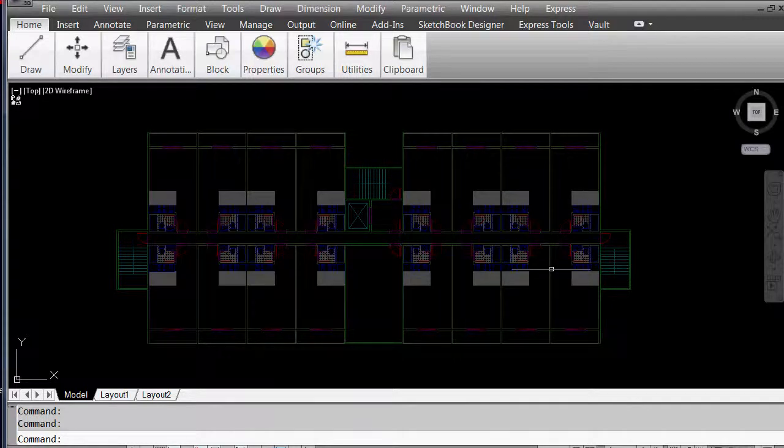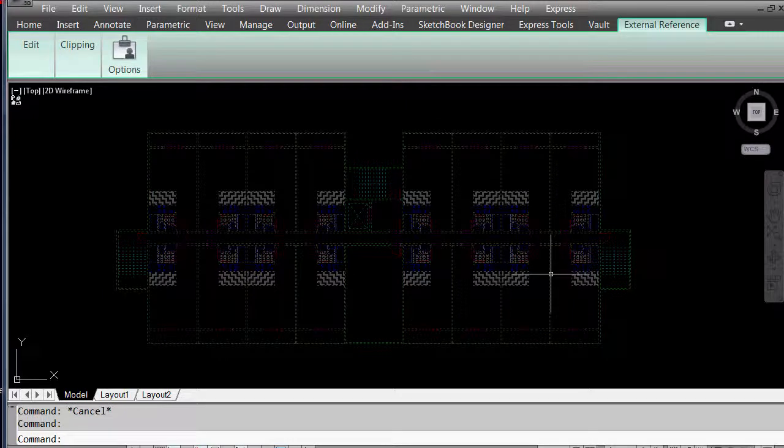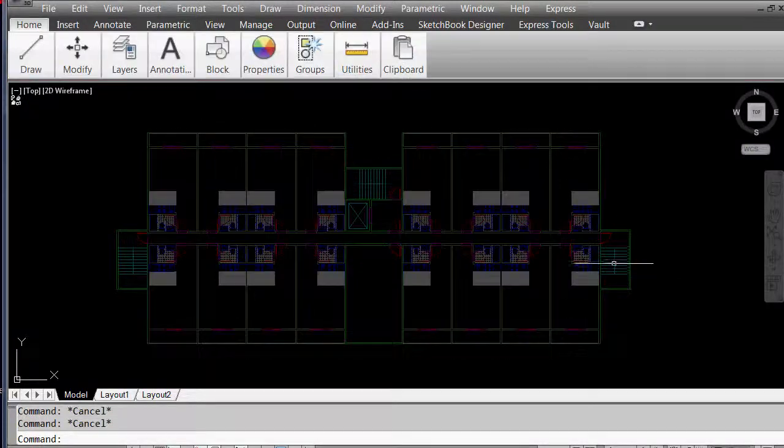All right, now let me list this, or let me touch the whole object. As I touch one entity, notice the whole block lights up, an X reference block, similar to the block that I did just a minute ago, but there's one subtle difference. This is an external reference. So as an example, let's say Pablo is working on these rooms here, rearranging them, but he's got the X reference in the apartment building complex.